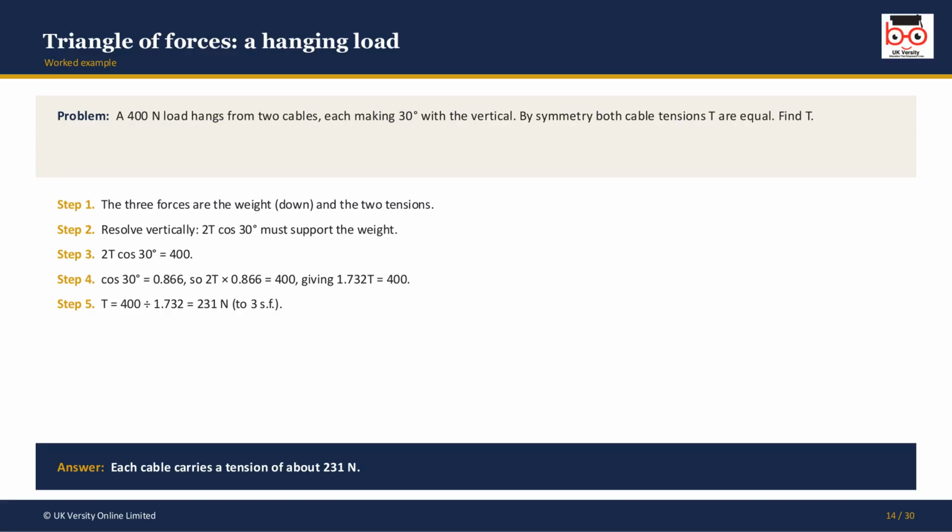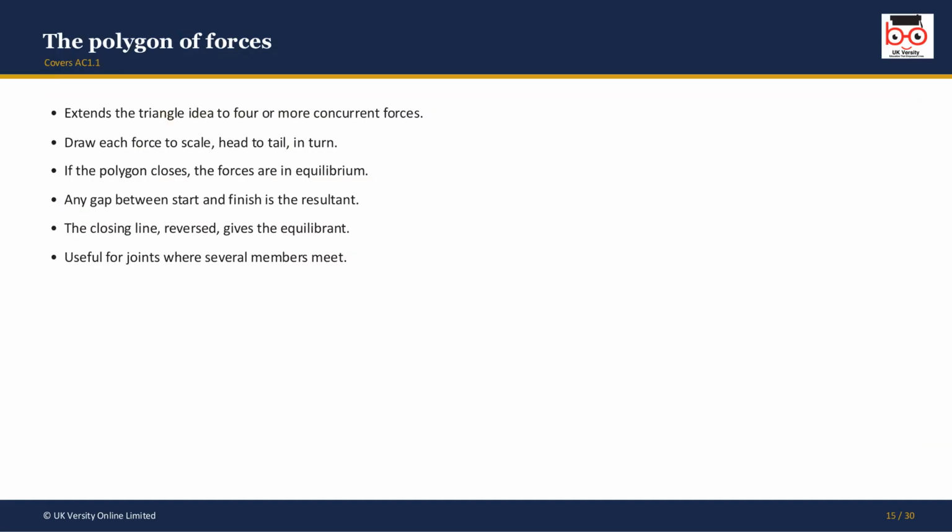Each cable therefore carries a tension of roughly 231 newtons. When more than three forces meet at a point, we simply extend the idea into a polygon of forces. You draw each force to scale, head to tail, taking them in turn.